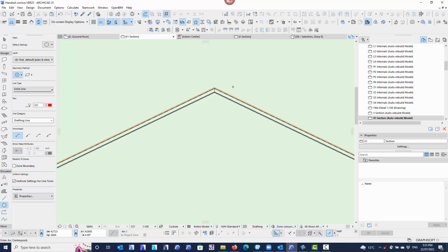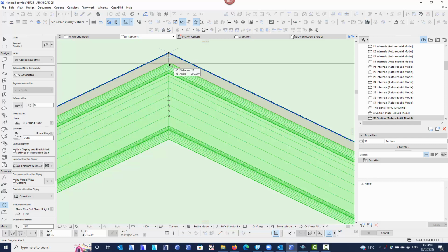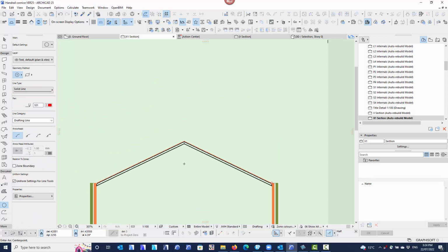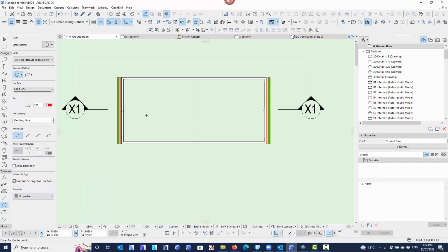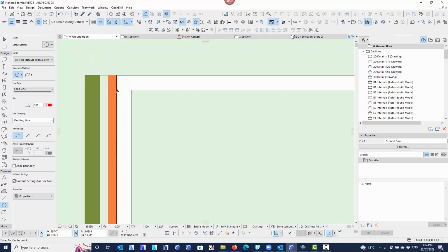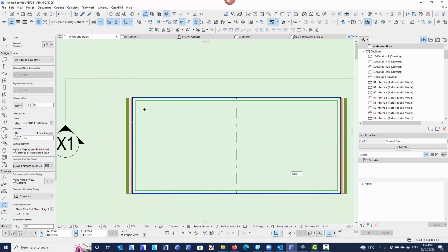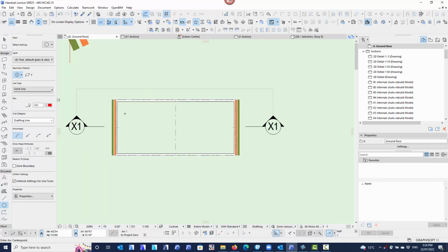Now is when you go and grab this cornice and you simply drag it from that point there to that point there. When you do that, you watch this associativity, it will all break and it will become static. That means it's no longer associated to the ceiling. So if I adjust the ceiling, the cornice will not adjust, or the railing will not adjust, which is not a bad thing. You can see here it's covered up half the wall. Now remember, you won't show this in plan, so it's not a problem. If it is, you could probably send it to the back and you'll now see the wall. That's using the railing tool, which is quite good.